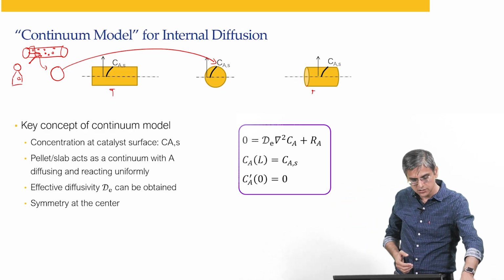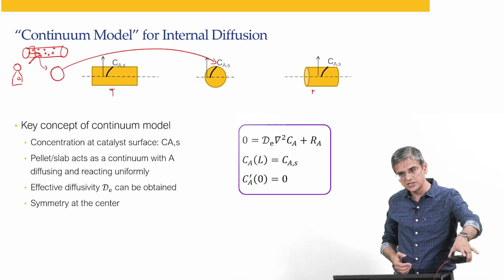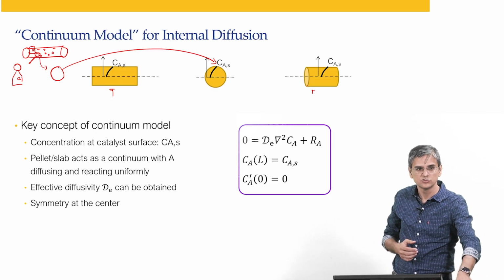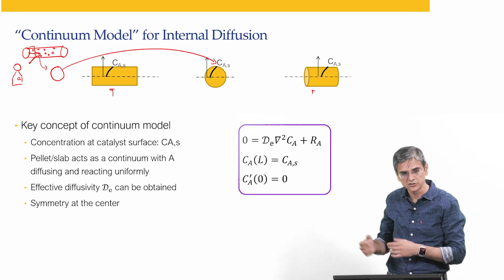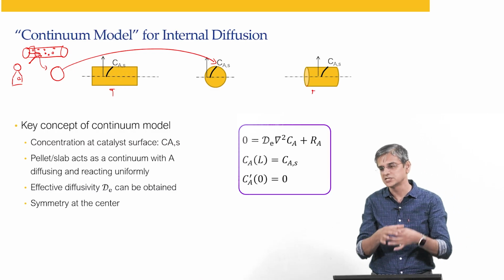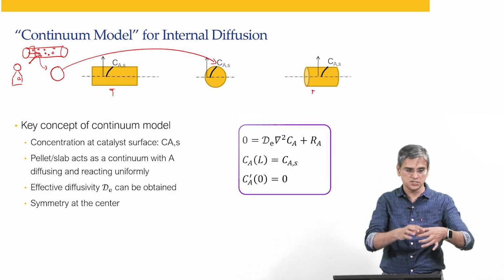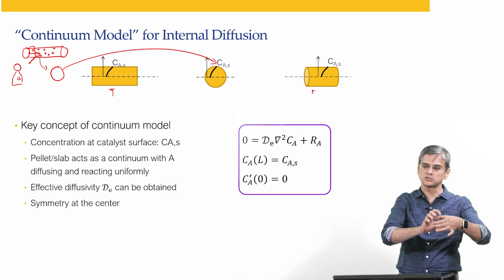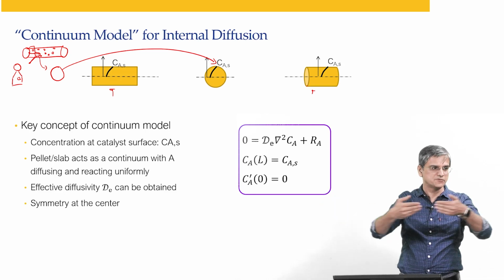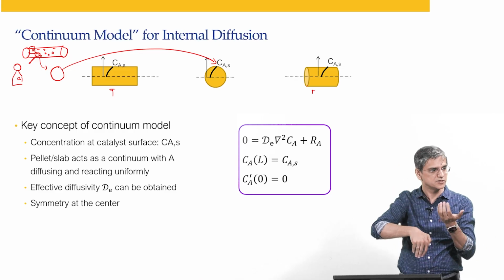So, the solution that we came up with was to make a pellet like this, called a hockey puck pellet. This was in the US, where they used to play, not field hockey, sorry, ice hockey. You might have seen those hockey pucks, right? That is why it was called the hockey puck shape. The reason is that the thickness was chosen such that it compensates for the fact that the heat transfer rate is much higher in this direction compared to this direction.